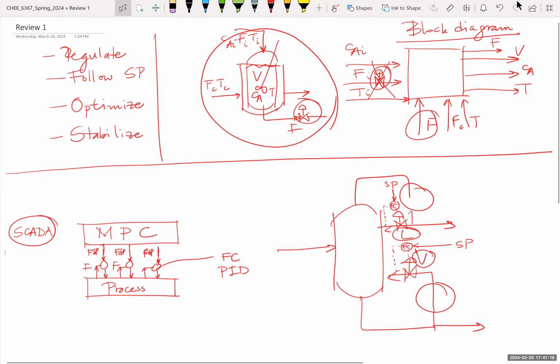But the thing is, you don't produce flow rates. You produce product, you produce purities, for example. So you have the distillate purity here, or the bottoms purity of the liquid, and all these things. So who is going to secure these things? Well, here you may measure that distillate purity and send it to a controller again.